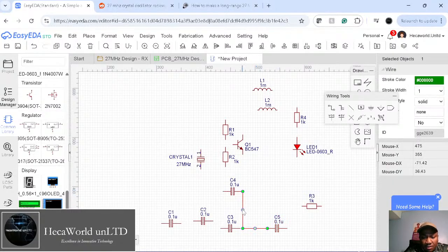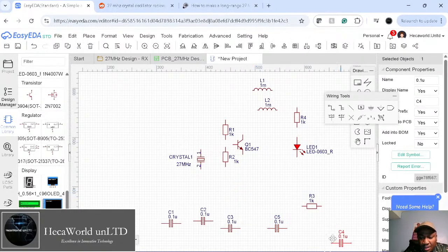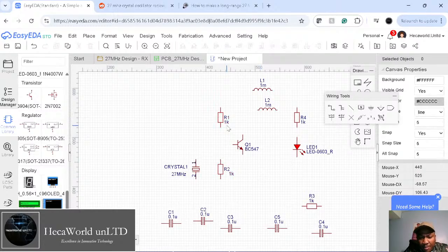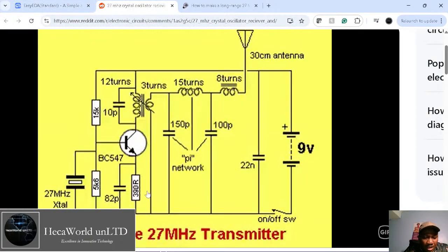All right, these two are connected already. We don't need to connect them yet. We'll figure out how they are connected later. So let's place it here so it's easy for us to connect and not have all the wires running into each other. So, all right. Then the next thing is we're gonna have a resistor. So this will be R3 and a second capacitor, C2, in parallel at the emitter. So this is collector, base in the center. The emitter has the arrow.